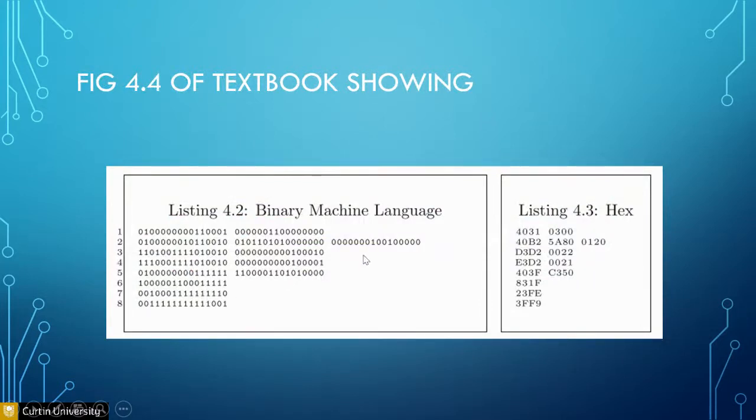But if you write in C, you don't deal with the hardware. You need to rely on the IDE to optimize the code. So what if the IDE is not really optimized and you really want to optimize it to a very high level? The IDE might convert it into unnecessary loops. If you want it to be optimal, you would actually try to program it in assembly.